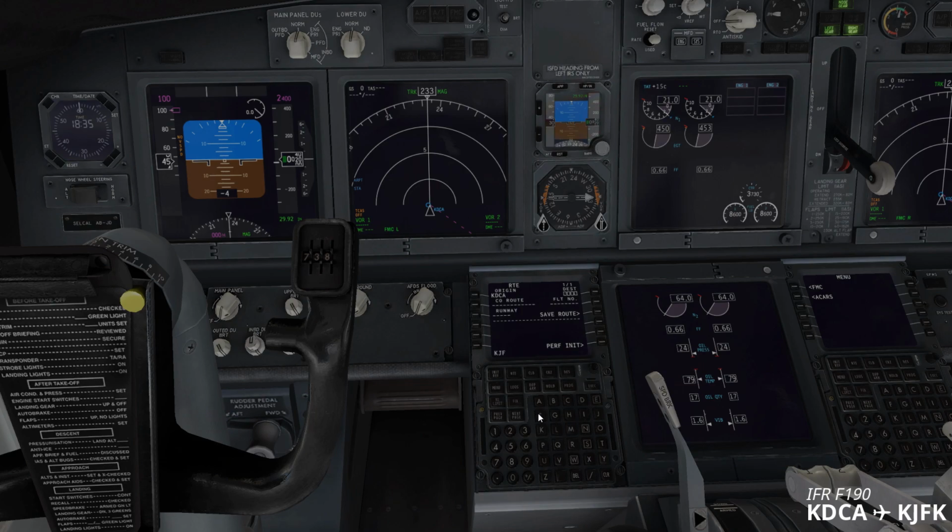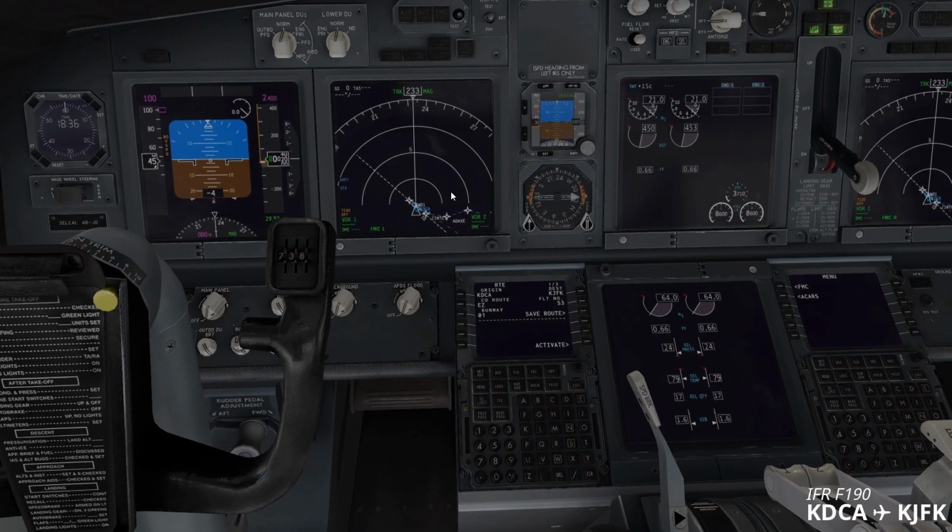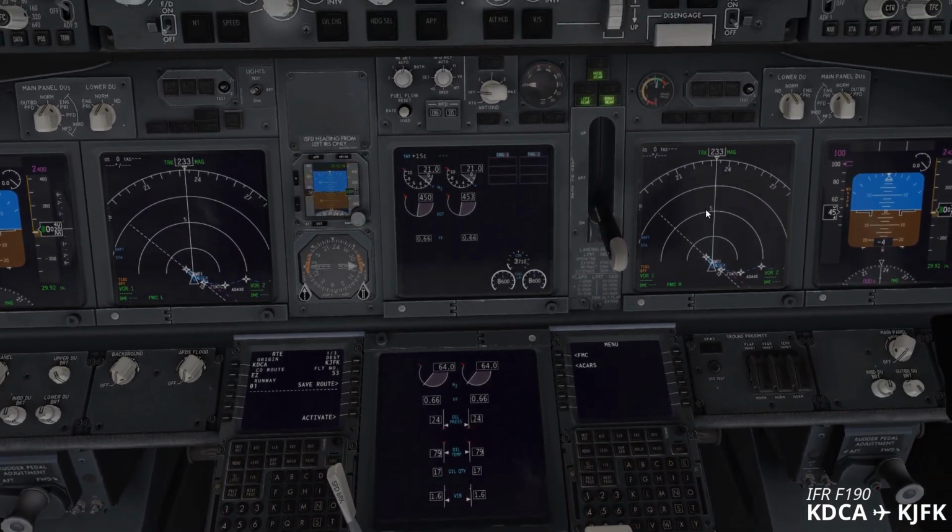And the flight planning we have done on Pilot2ATC, we're going to bring it over here. That'll cut down a lot of work. I'll just put a flight number. This is completely optional. Just put that as by itself, SIM3. And now here is where we'll put the flight plan we exported in Pilot2ATC at the beginning. You just put the name without the extension, and see everything got loaded to the FMC.